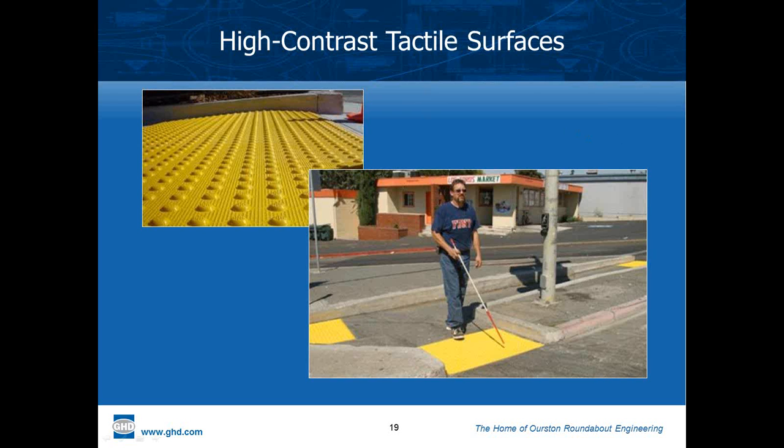Single-lane roundabouts are said to be an accessible intersection from the U.S. Access Board. At least that was the original language in some of the guidelines published on accessibility. I'm not sure that I can agree with that. Anytime you have a pedestrian that's crossing a roadway, there's the chance that vehicles won't stop, and even if the crossing is short, as it would be for single-lane roundabouts, I would still be concerned about the accommodation factor.